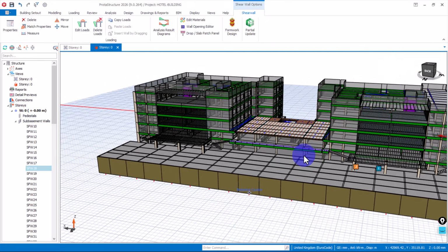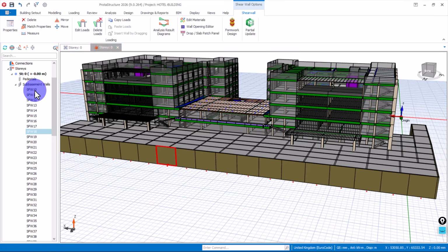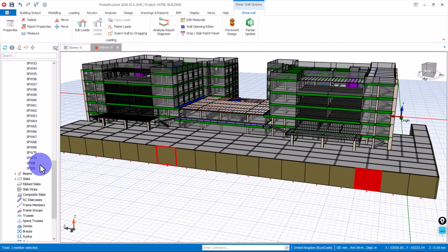what I will do is I'll come to my structure tree, which is around here. Now note this one that we just added is soil 18, so I will have to skip it when I'm doing all my auto selection. I will then click on this one here, on this 10. Now scroll down, go to the last one, and hold my shift key to make a multi selection.